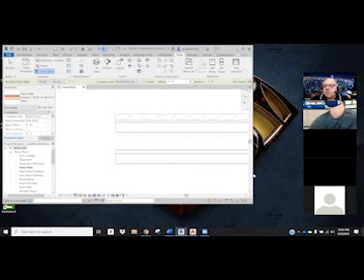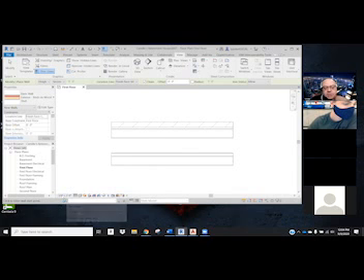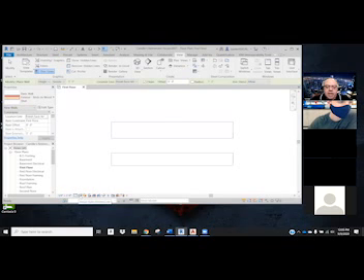All right, all of you, the rich and the poor, the young and the free, the bond and the bold, whatever. If you go down to your bottom left-hand corner of your drawing area, you'll see where it says 1/4 inch equals a foot for your drawing scale. And then there's probably a box that looks blank white and a cube. Those two are your view levels that we work at. So what we're going to do is adjust those.